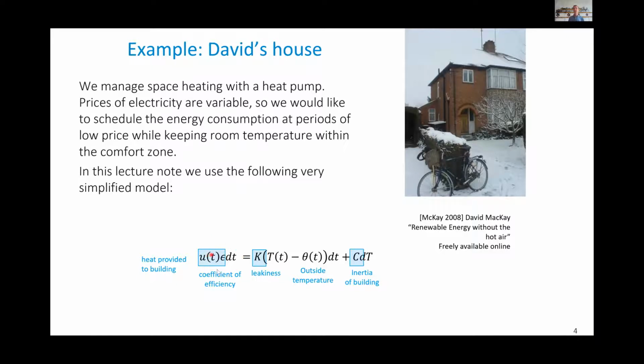If you have a heat pump, it's more efficient because, as you know, a heat pump is extracting heat from the environment. So if you give 1 watt hour to a heat pump, it will put into the house more than 1 watt hour, depending on the technology of the heat pump. It will be between 2 and 3. So this is the multiplier that we apply to the energy. That's the net thing that is input into the house.